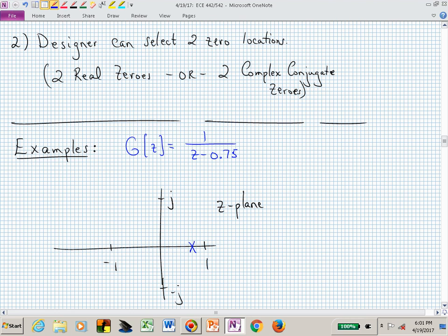Can you stabilize this system with a constant controller, with a proportional controller? If this plant is in a closed loop setting with an adjustable gain k, can you stabilize this system? Yes, the root locus for a proportional controller is just all to the left. You obviously have a limit. You can't crank up the gain too much. You would want to keep the gain less than what would drive you outside of z equal -1. Is that clear?